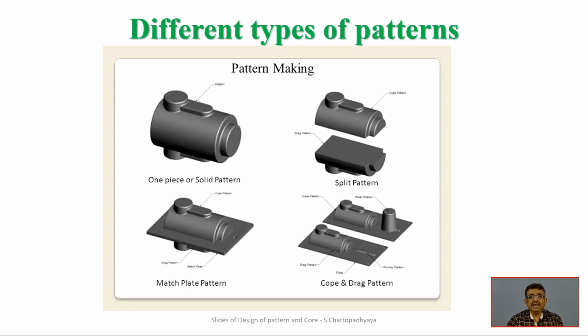But only in case of investment casting, one does not have to remove the pattern, because the pattern is melted away at elevated temperature. That is the advantage of investment casting, but the problem is that every time we have to make a pattern, so that will be a sacrificial pattern based casting.